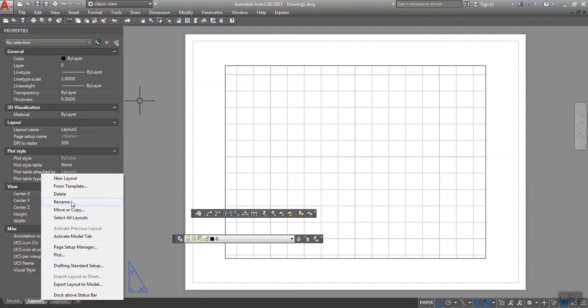So the paper space tab is, as I just mentioned, the name paper space. Each sheet is just like every layer. So layer 1, you can rename it and you can put cover sheet. That is your sheet. And as you're creating your title block, it has to be created on your layout page or your paper space page, not your model space page.